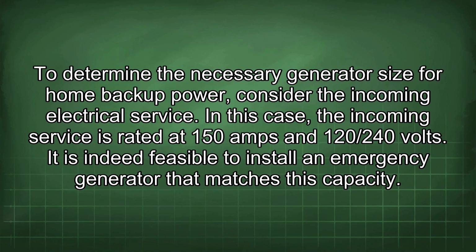To determine the necessary generator size for home backup power, consider the incoming electrical service. In this case, the incoming service is rated at 150 amps and 120/240 volts. It is indeed feasible to install an emergency generator that matches this capacity.